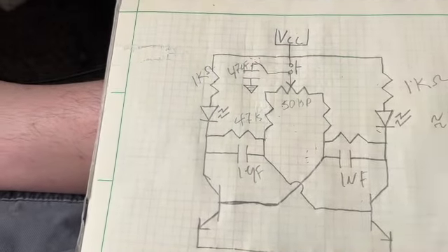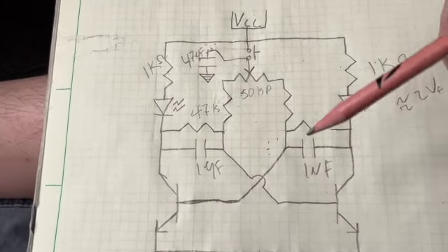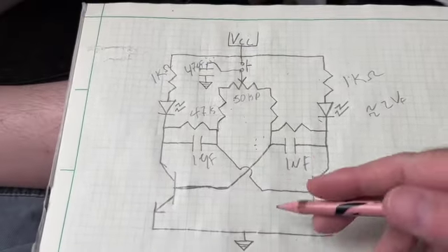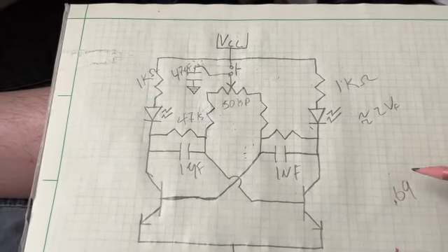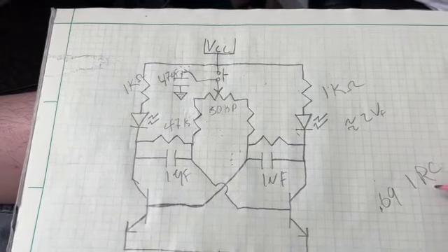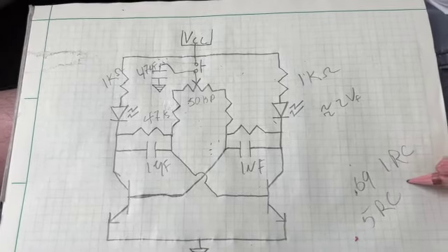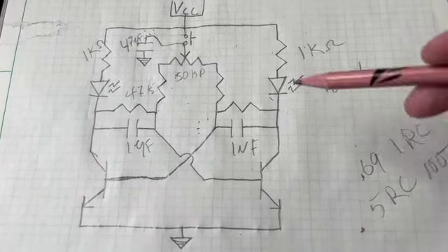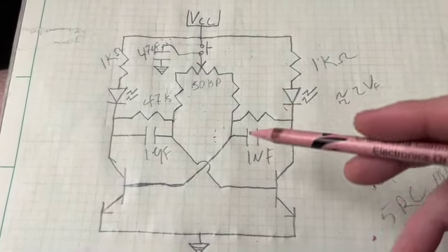So there is a formula to get the frequency, and that's available anywhere you want to look online. I will tell you that it has something to do with the capacitor getting about 69% of its charge during 1 RC time period. And it takes 5 RC constants to get 100% charged. So that should give you a clue as to how you calculate the total frequency that you're going to get. However, it's not really that important.